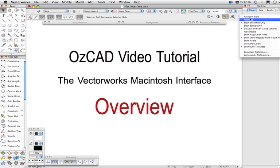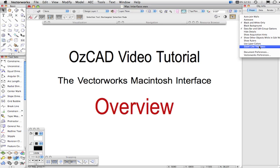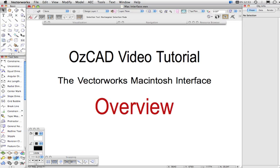So these are the options that you can add: autosave, black and white only, data bar and edit groups, and so on. Zoom line thickness. You can also directly access document preferences and Vectorworks preferences from this drop down menu. So if I choose to remove zoom line thickness, I just choose that and it will disappear as one of these options. If I add it back in again, it will come back here. The order that these appear here is controlled by the order that you add them.